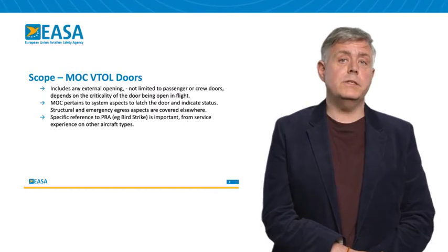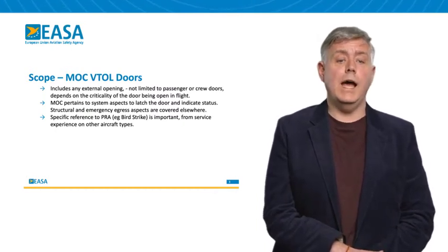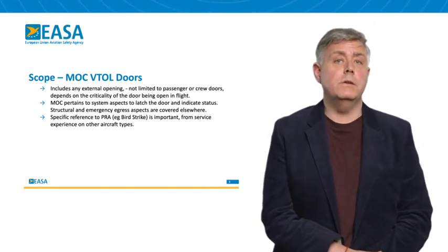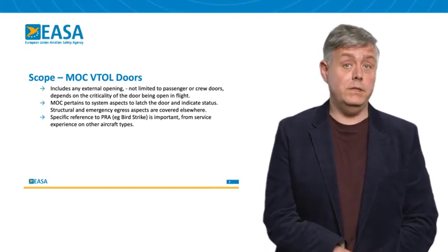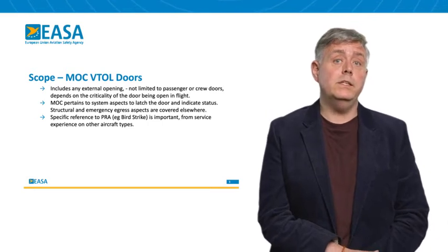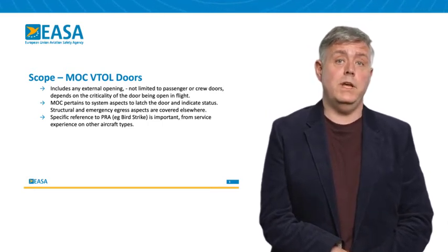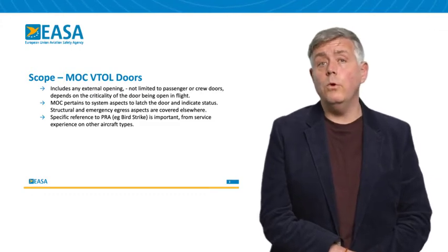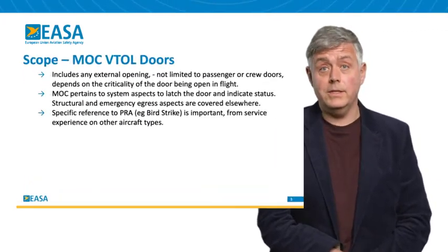Service experience on other vehicles has shown that particular risk aspects, for example, but not limited to, bird strike, are important for the door retention and indication, and these therefore form part of the means of compliance.